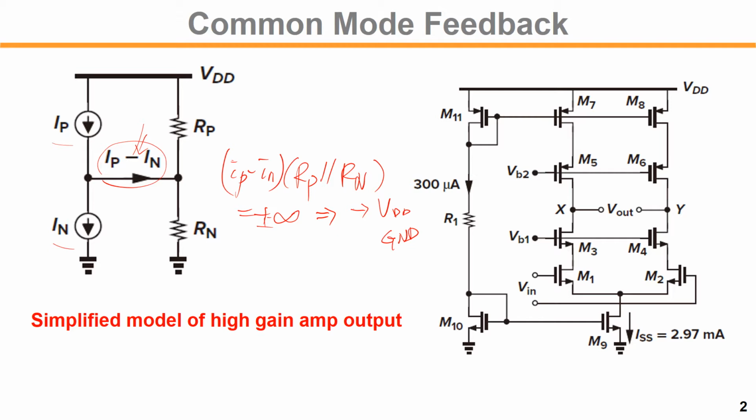For example, on the right hand side, telescopic amplifier, if you look at this, you can immediately identify the pull-up current source and pull-down current source. Ideally, this level must be exactly matched to, let's say, ISS over 2 and ISS over 2. But in reality, there is some mismatch, right? What kind of a mismatch can contribute such kind of error? For example, different VDS, right? Different VDS on the current source, current mirror, will generate the current error, right?